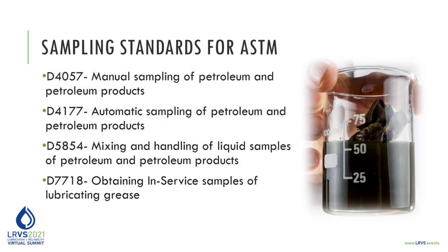ASTM has established 4 standards for sampling. The D4057, manual sampling for petroleum and petroleum products. The D4177 for automatic sampling of petroleum and petroleum products. D5854, mixing and handling of liquid samples of petroleum and petroleum products. And then the D7718, obtaining in-service samples of lubricating grease.